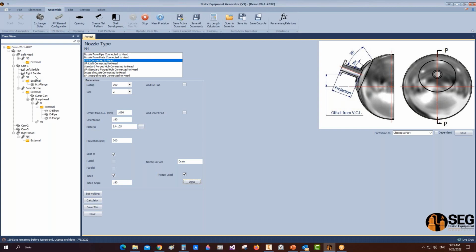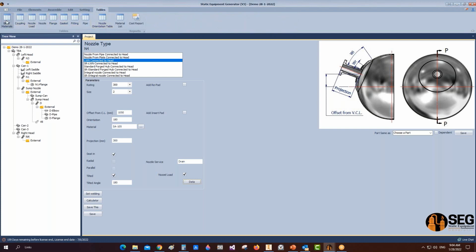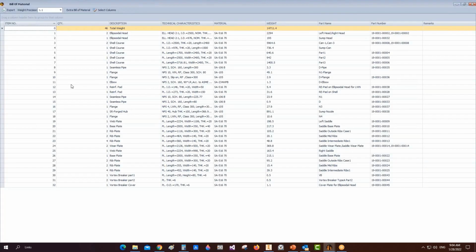this, and when it finished, the color of this button will be converted to the green color, and those buttons will be activated again to the blue color and red color for stop. Okay, so here it's done, and now the information sent to disk inventor items. And here to understand this point, here for example, for the seamless pipe, this pipe, which is related to pipe D, here it takes the item number 8. So when you create a balloon for this element on the drawing, this item number will be reflected to the drawing.